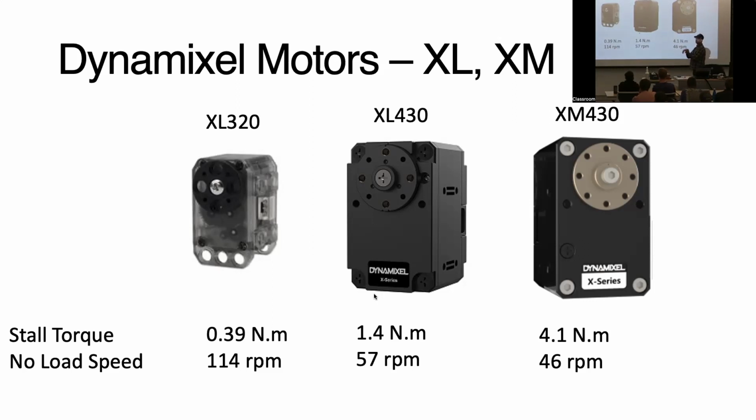And then the wrist motors are this, because now we don't have to have much force. All of the other motors for the arm we're going to use for the Armlab are the higher torque XM motors. So these, actually, we have two motors on the shoulder, because that's where we need the most torque, right? That's carrying the most weight, because it has to support the entirety of the rest of the arm, the weight of all the linkages and motors down the serial chain. And then the elbow is also one of these motors.